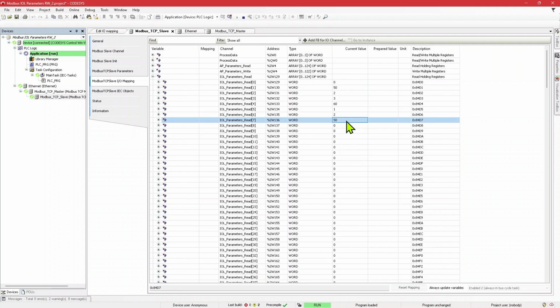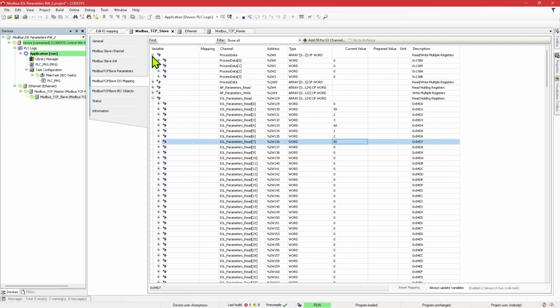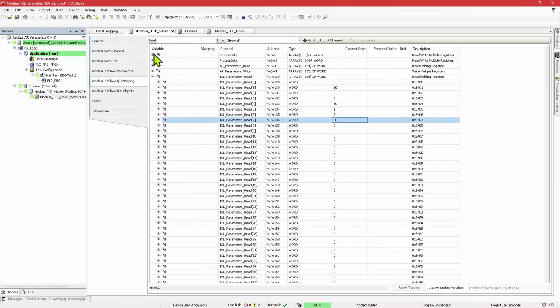So it's 50. Unfortunately, you cannot see it here, but I have the sensor, and I'm going to try to put it against an object. I'm seeing that right now I receive a signal that the object is detected when I'm maybe about 2 inches away from the object. That's when the signal turns on. Can we see the signal here? No, we cannot. Don't worry about it, because I said that we were not going to go into process data, but I am seeing the signal here. So approximately 2 inches.